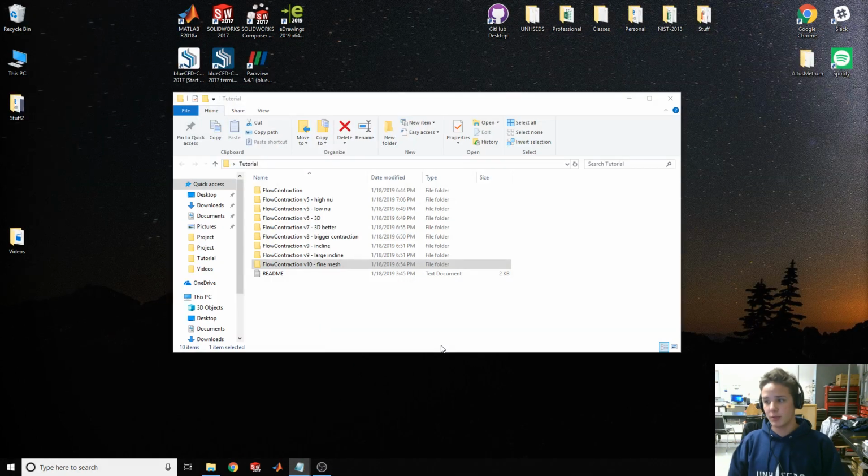For us, we're going to be using pimpleFoam, which is a specific solver. It is for incompressible flow, and it basically uses the SIMPLE solver, which a lot of people are well aware of, but it also incorporates PISO, which is a different solver. A lot of CFD uses different solvers as basic core ones, and you can mix them up because they all have different strengths and weaknesses. We're going to be using pimpleFoam because it's a large time step transient solver.